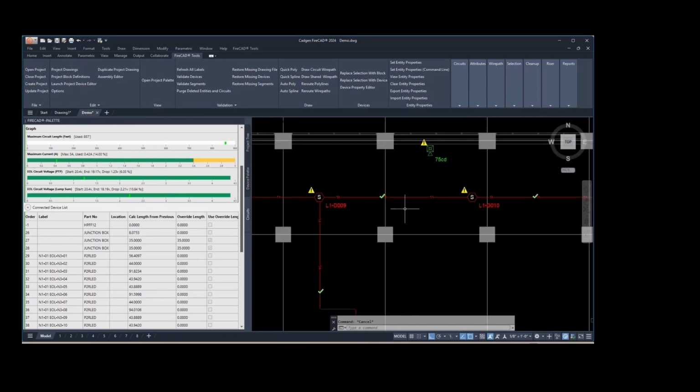By the way, the other thing that's important is it's got to be a single polyline. It can't be like three pieces, like one going up and then an intersection and another going down like that. But if it's one polyline continuous from here to here, yeah, you can do that. But you had to assign that or tell that polyline that it's going to have old calculations, right?